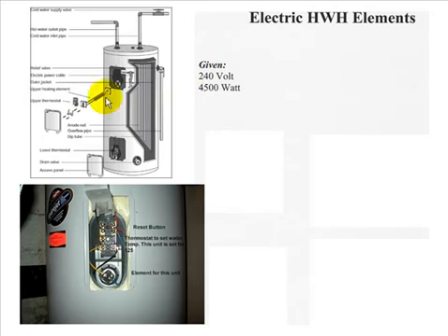240 volt, non-simultaneous operation, which means that both of them never operate at the same time. They're non-simultaneous, okay, and the thermostats make sure of that. They're 240 volt, 4,500 watt. 4,500 over 4,500. Very, very common. 50, 70, 80 gallon, whatever it is, hot water heaters.